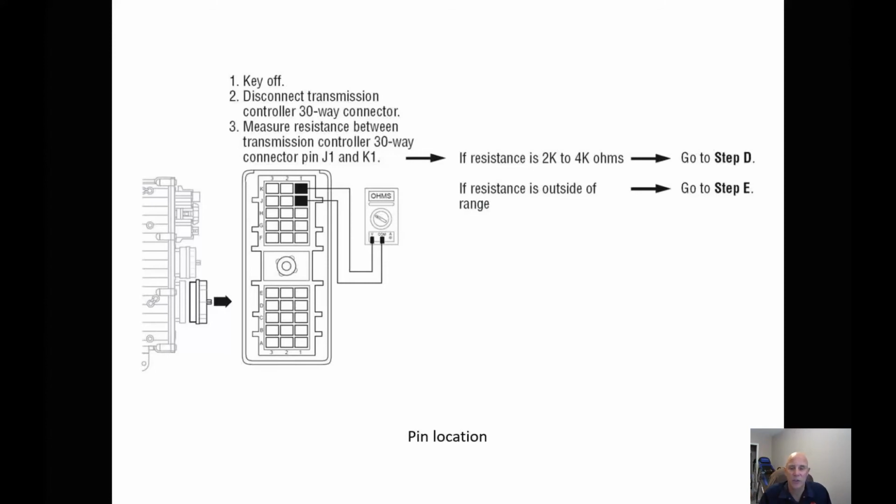So understanding the system, again, being able to troubleshoot and understand what we're looking for. If we're doing step-by-step procedure checks, for instance, here we're checking pin locations. Checking the resistance, don't miss a step. If you think, oh yeah, well it's probably going to be good, always check all of them to make sure that we verify that the proper sequence of events have been done and we've checked everything, so we're not going back double checking something that we've already checked, or just don't forget anything. And that finishes off shifting of transmissions and automated transmissions.